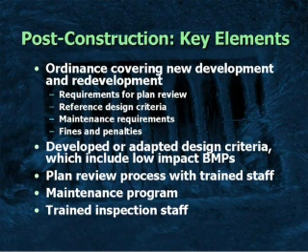And again, as John talked about, the plan review process can be integrated and should really be integrated with the construction process. We're breaking it out here simply because that's how it's laid out within the regulation. And then maintenance is probably the biggest challenge here of all, to make sure that these BMPs are maintained over the long term. And again, communities have a strategic choice here, whether they want to take on a lot of the maintenance burden themselves and have better control, but of course the cost of that is relatively high. Or whether they want to try to get citizens and commercial establishments to take on the maintenance burden, which maybe has lesser costs, but also requires detailed maintenance agreements and an ongoing education process and inspection process to make sure that these things are getting done. So the whole maintenance question is probably the biggest challenge here in putting together a post-construction program.